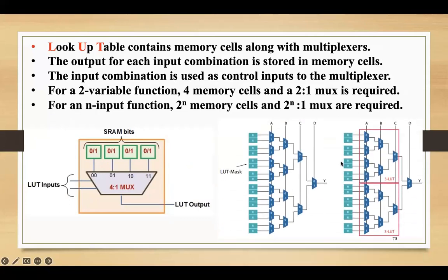If you look at it on a larger scale, this is how it looks. You have your A here, then you have 0, 1, all interconnected, just like how you can implement, say, a 16:1 mux with the help of 4:1 muxes, where you combine them and the outputs are taken to the next level. Again, you will need another mux to select between those outputs, and the final mux between the previous multiplexers.